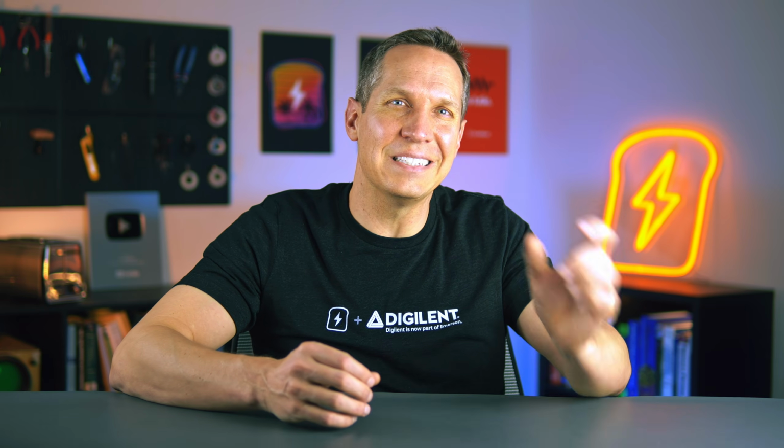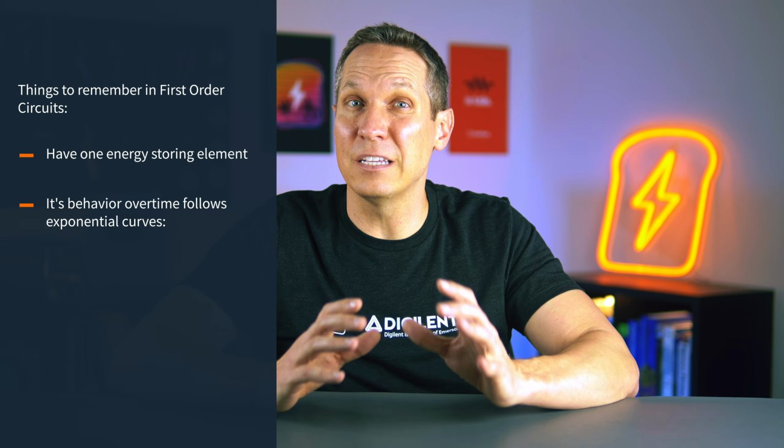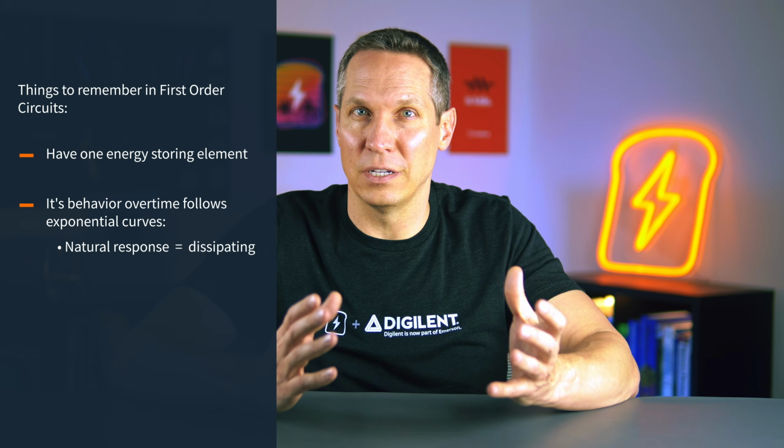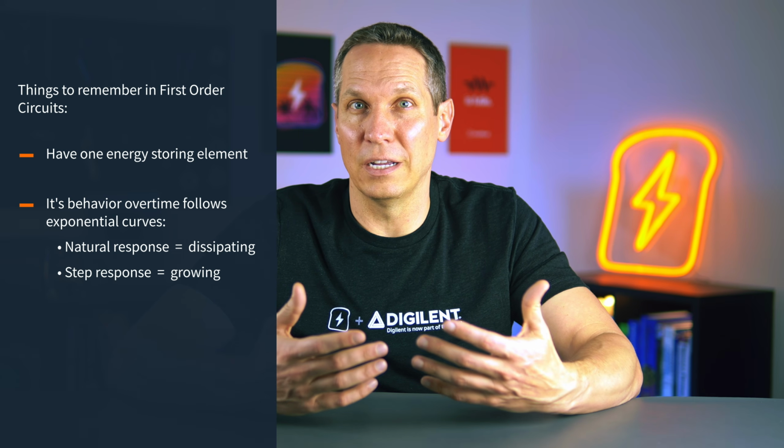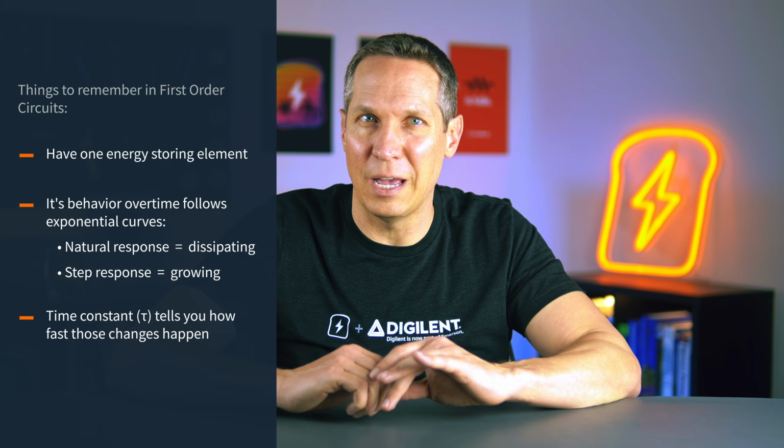As we go through these DC circuit concepts, it's very easy to get behind, start getting things jumbled in your head, and get lost in the details. When you're doing these problems, the math is no joke, but I encourage you to take your time and make sure you're working to understand the basic concepts and tying them to these simple math equations I shared. So the key things to remember are that first-order circuits have one energy-storing element, its behavior over time follows exponential curves, dissipating when looking at the natural response, growing when looking at the step response, and the time constant tau tells you how fast those changes happen.